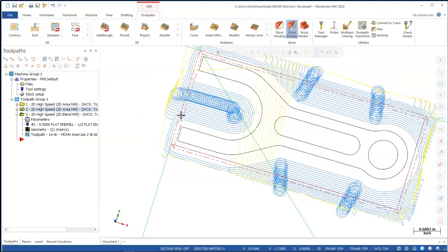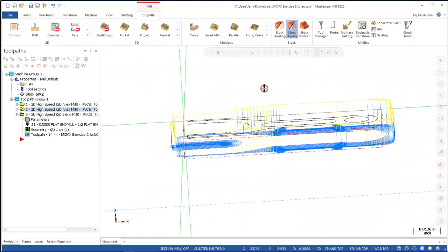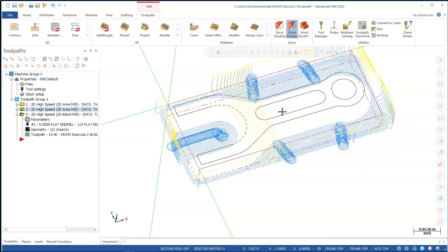So if the machine's not capable of 120 lines of look ahead, then you're not really gaining a lot of advantage with getting really aggressive with the high speed. There are lots of advantages with doing the high speed, even at the lower look ahead, because you're going to have less tool load. You're going to have that increased tool life and wear. But it's something you have to experiment with. I mean, the technology, the Vericut, and some of the other first trochoidal cuts have only been out for, I would say, less than 10 years in an industry that has traditionally been, you plunge in, you walk the tool around, you retract it out, and it doesn't do all this fancy stuff.